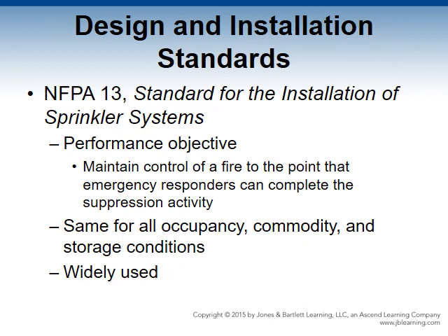Sprinkler heads should cover all spaces in a building, including concealed combustible spaces, attics, and in some instances, the spaces above or below the ceiling. The same requirements and performance objectives apply to all occupancies, commodity, and storage conditions covered by the standard.